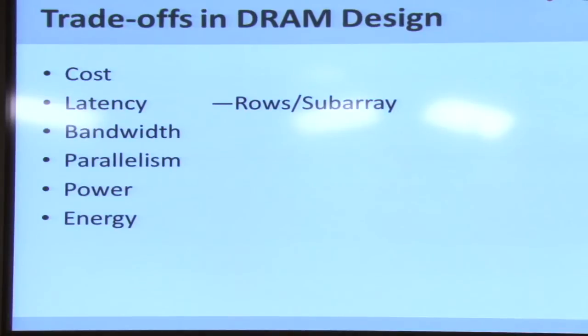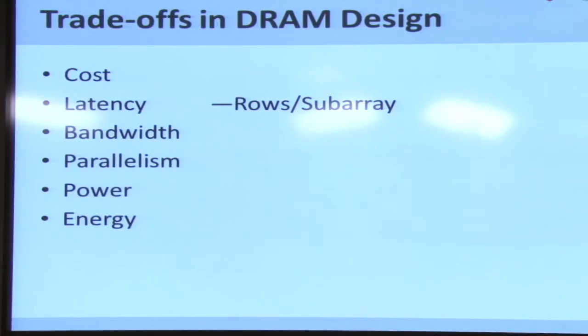I think in previous days they used to have single inline memory modules, which means they had only 8 chips in the module. And like he points out, these 8 chips form what is called a rank. Okay, and the 8 chips on the other side form a different rank. So essentially, this particular module has 2 ranks of 8 chips each.